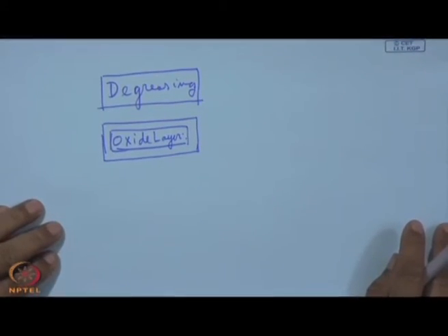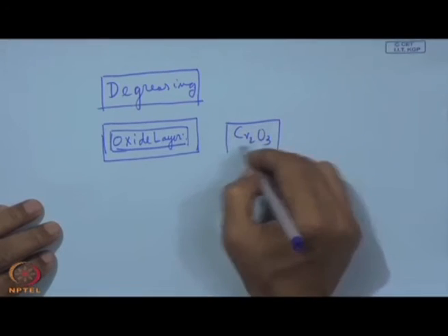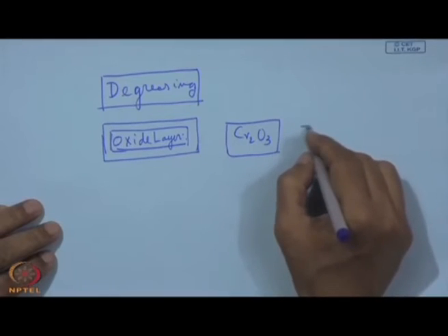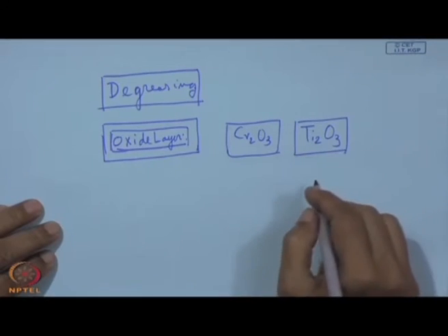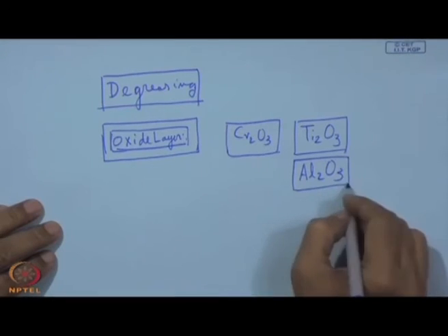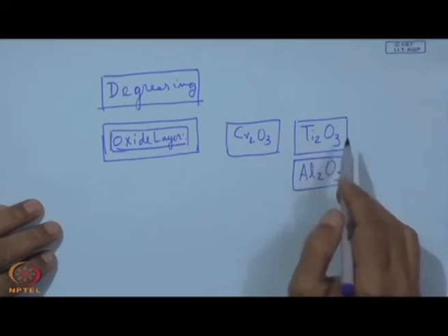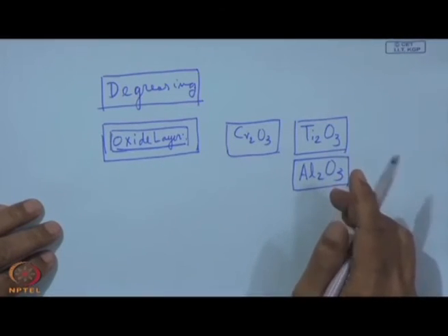If one has to get a good coating, say for example on stainless steel, it will not be a very easy task, because on stainless steel it is Cr2O3, and then deposition will be extremely difficult. If we have some titanium alloys, it can also be Ti2O3. If it contains aluminum, then also it can be Al2O3. So, if this is present at some atomic level, then this will become a non-wetting surface and we will end up with globule formation.